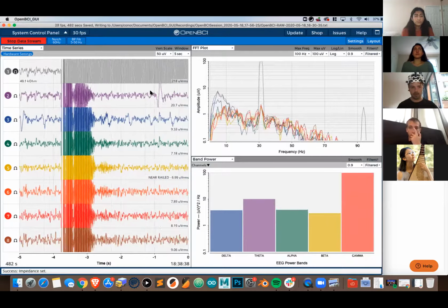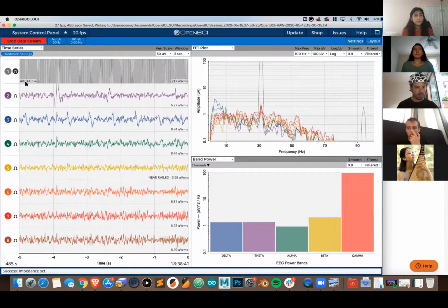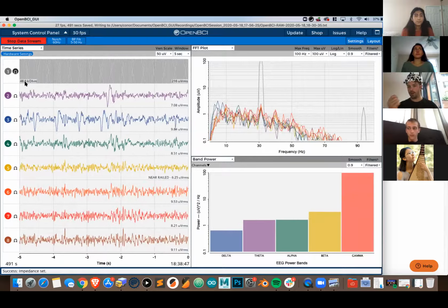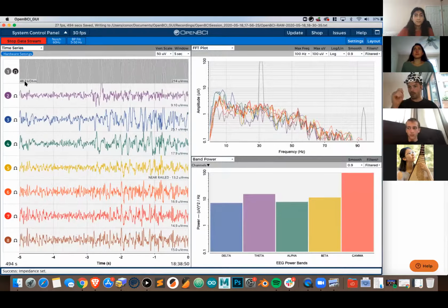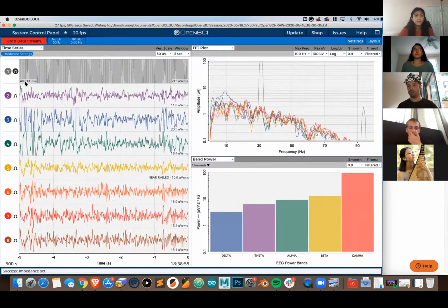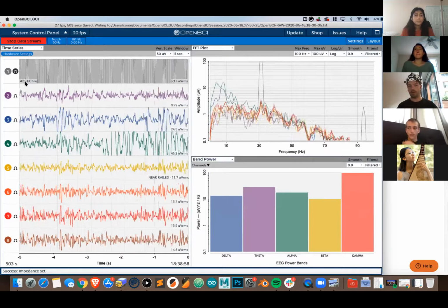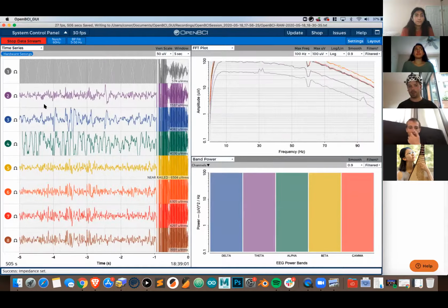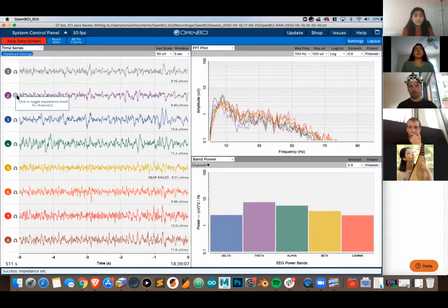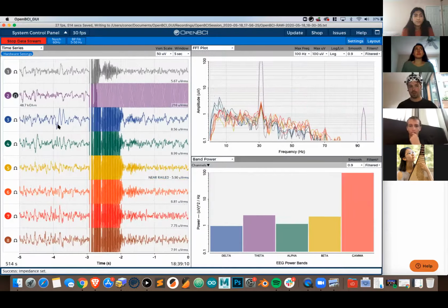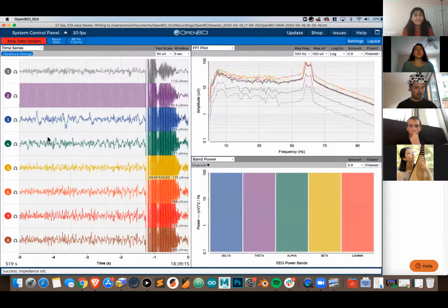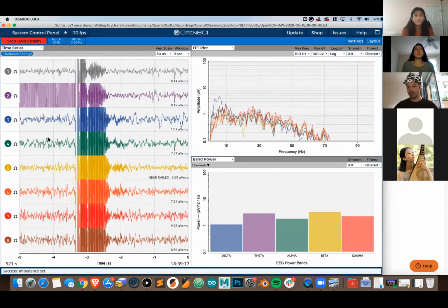And right now, here we go. So we're looking at 48 kiloohms, which is, if you have a wet gold cup electrode, like you use paste and you stick it through your hair or on your scalp, you'll probably get an impedance that's 1/10 this. So below 5 kiloohms. And actually, as a cross comparison, let's turn on channel 2 and see what channel 2 is, which is comparable, suspiciously close. And yeah, so that's how you do the impedance check.